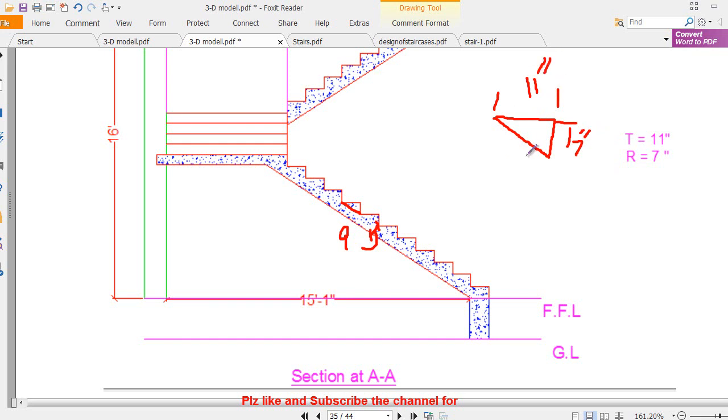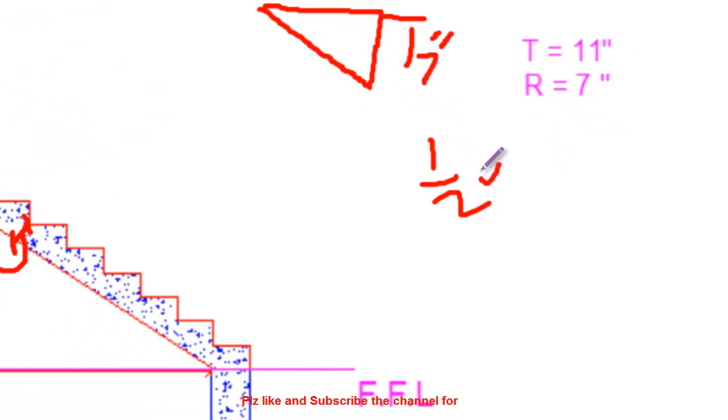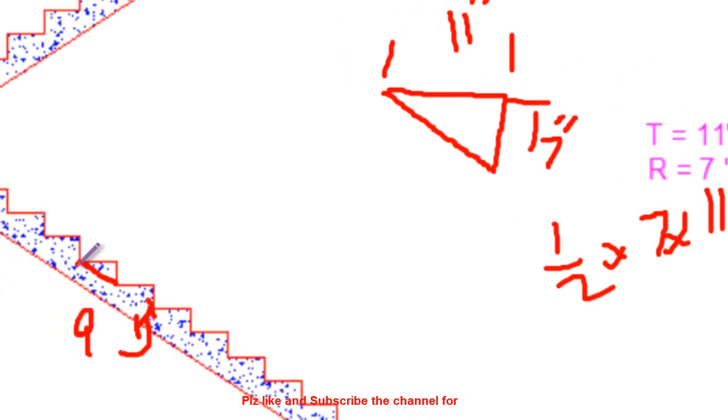Okay, now the weight of this step is basically simple. You just need to calculate the area of the section times the density of concrete, and the density of concrete is solid concrete. Okay, so you can use 145 or you can use 150, 140 as well. But here you have the slab, the waist slab. This is a rectangular portion.